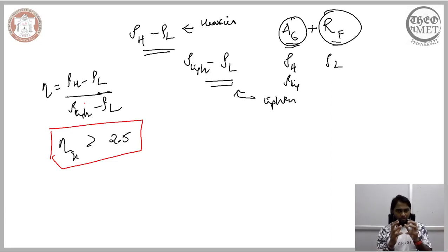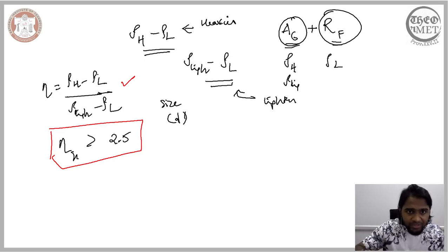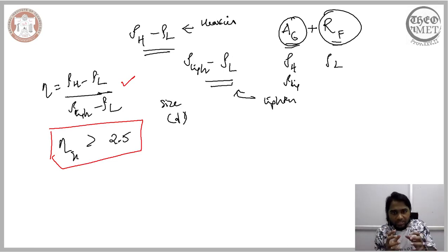Now when we are talking about the efficiency in this context, the efficiency of the gravity separation process, which is exclusively governed by the density of the particles and the density of the medium in which these particles are suspended, we are actually overlooking something. If you consider rigorous treatment of the efficiency, then in this expression here, it overlooks one factor, and that factor is the size of the particles. This expression exclusively considers the density, but what it overlooks is the size of the particle.